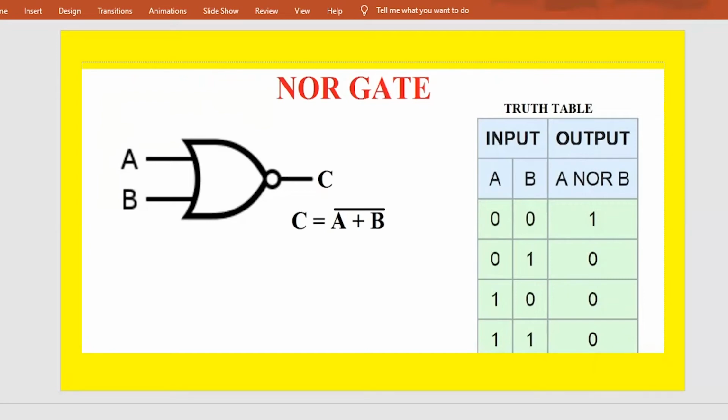There are 3 symbols for NOR gates: the American symbol, the European or rectangular symbol, as well as the deprecated DIN symbol. So for more information, we may see the logic gate symbols. The IEC symbol and ANSI symbol for the NOR gate is a standard OR gate with an inversion bubble connected. The bubble indicates that the function of the OR gate has been inverted.